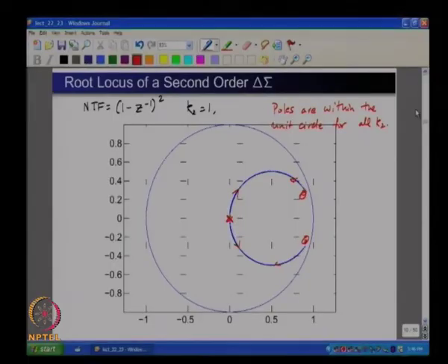Is this clear? Okay. So, we are now in a situation where we have the following. We really like (1 - z^-1)^n. Why do we really like it? The in-band noise is reduced by a large factor, correct. If you have (1 - z^-1)^n, you get n plus half bits every time you double the OSR. So, it seems like a really attractive thing.